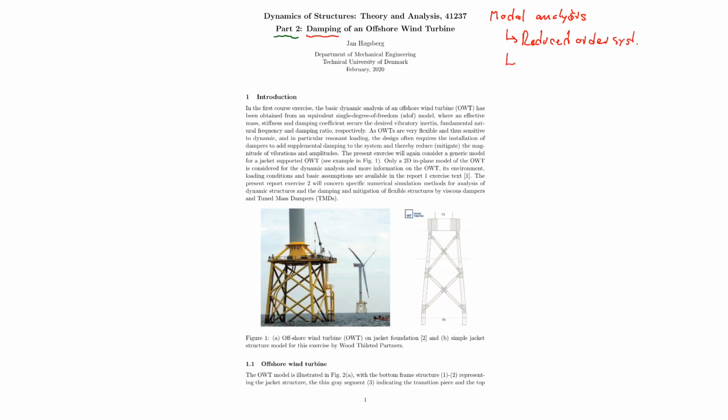It's a reduced order system. That means we're going to apply some kind of system reduction procedure, and we're going to use the dynamic static split of the degrees of freedom into 2 parts, and we'll only analyze the dynamic part dynamically. Then we'll have a second part that concerns damping, and first we introduce a pure viscous damper acting on the structure, and the idea is, of course, what is the optimal viscous parameter for this device to actually introduce maximum